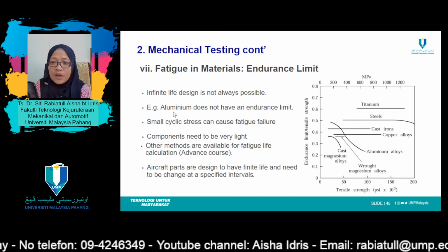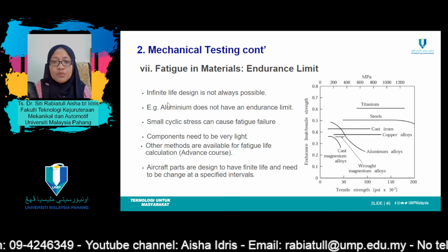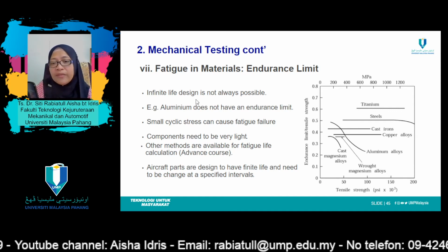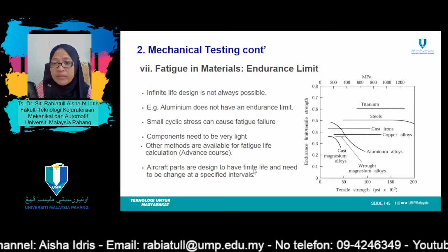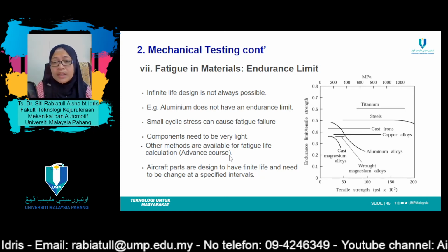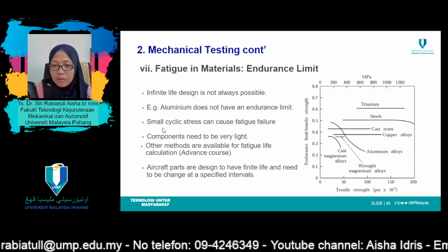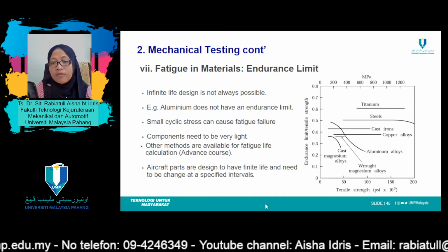And the endurance limit actually refers to infinite life design. And this infinite life design is not always possible for any type of material. For example, aluminum, just now, does not have an endurance limit. Therefore, small cyclic stress can cause fatigue failure for these types of materials.